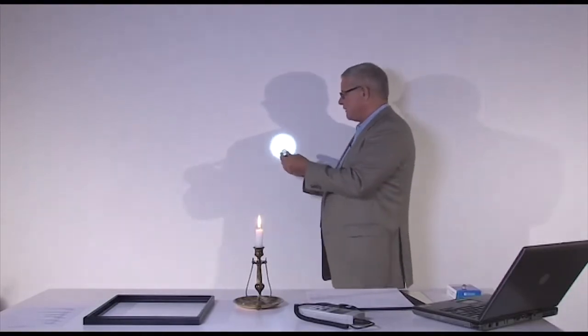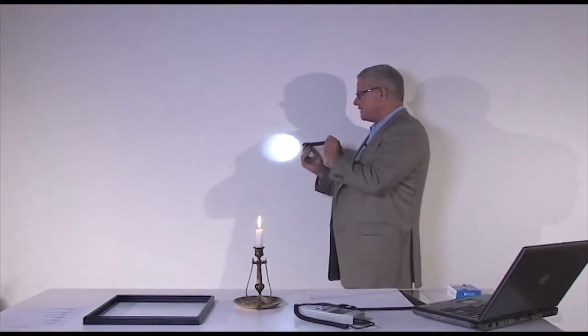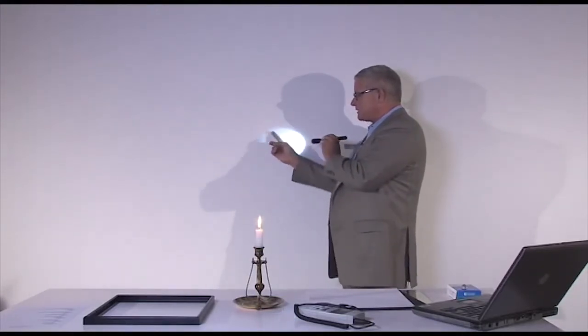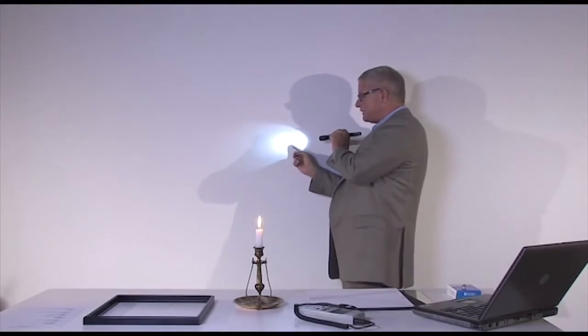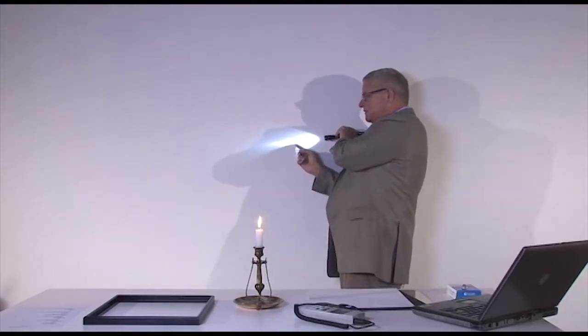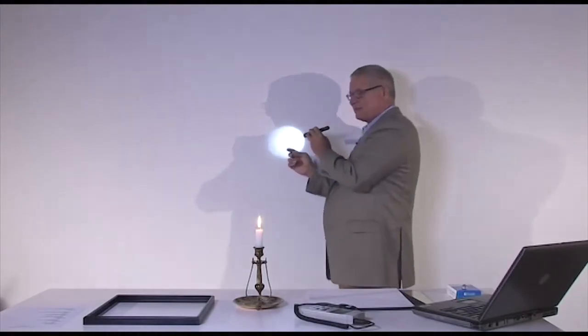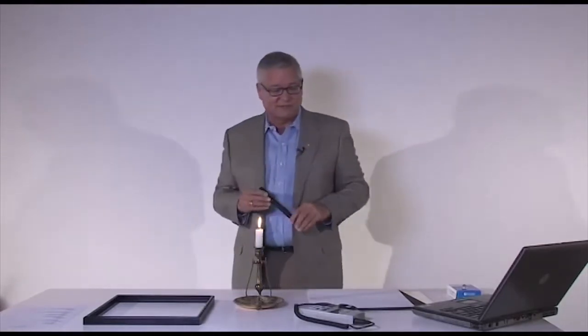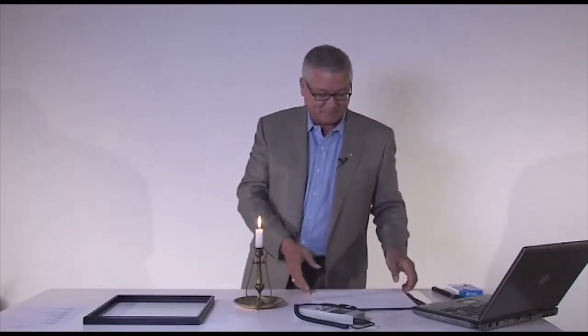It also varies, however, with the angle at which the light hits that surface. And you see that as I increase the angle, the light is covering a much greater area. And looking at the very center point, I can practically project that across the entire wall. The density of that light, therefore, is greatly reduced as a function of the cosine of that angle. We'll revisit this when we talk about calculations.